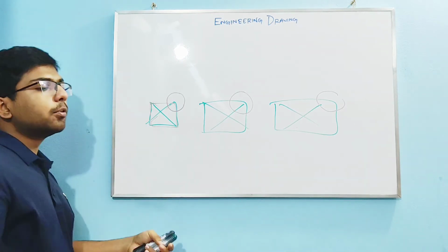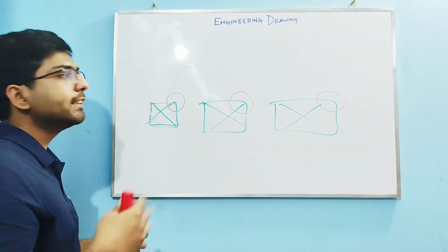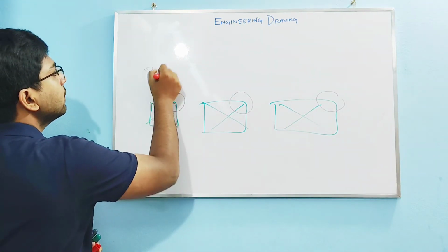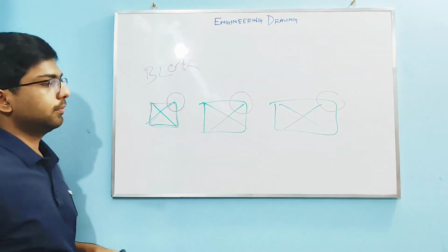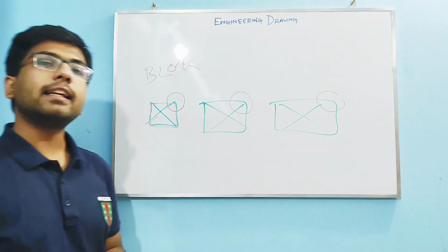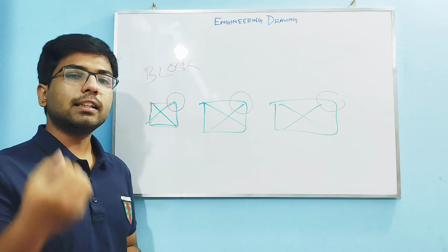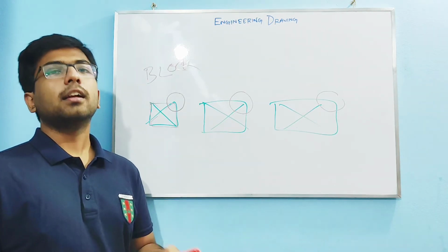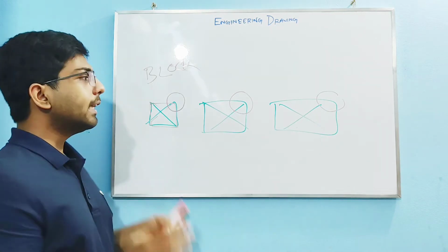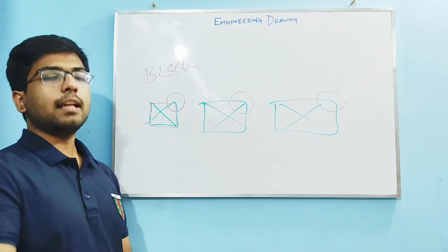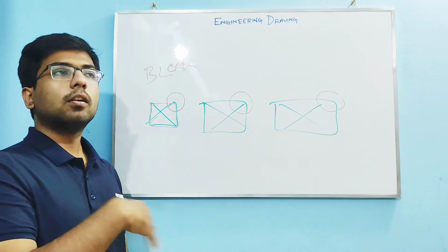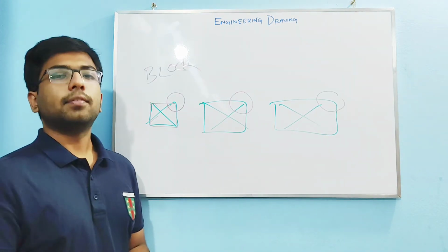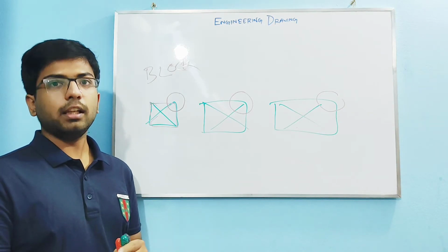Actually, we cannot say it is more useful. This basically depends on the scenario we are facing. Okay. So this is the basic block command. Block is like creating a template of something. You can create as many blocks as you want and save them, and whenever you change the template, all the instances of the template in your AutoCAD will be changed. This is the block command. So now we will see the demonstration in AutoCAD.